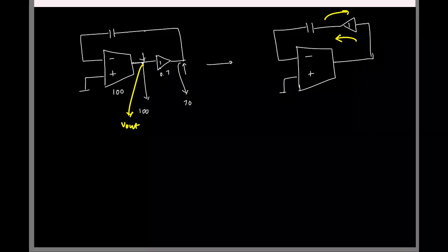Can't you put a diode, a simple diode? If you put a diode, again, see, your DC biases will also be screwed, and you need to make sure that this diode is forward biased, right? Your signals can go negative also, and this voltage has to be set properly. You can do it, but you need to set this voltage properly.